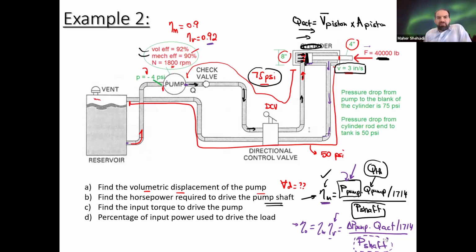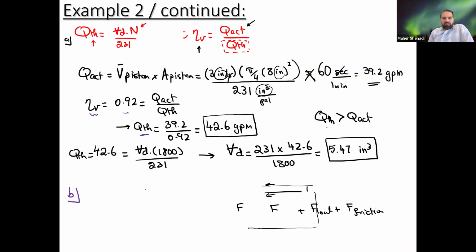So I'll need to have the pump to overcome this pressure and to be able to push this load and the return pressure. Now, what's the relation between P cap and P retract? Anyone recalls how we calculated that side? We said we don't do pressure balance, we actually do force balance, and that's basically coming from, so if that's the piston, I'm going to call this P cap, PC if you want, that's the cap side, and here I'll call it P retract, that's the piston.